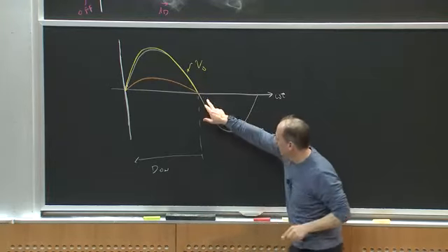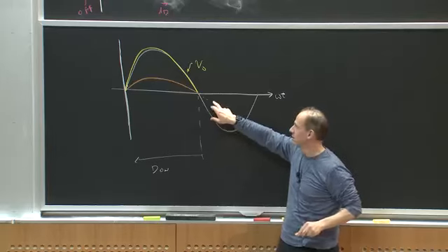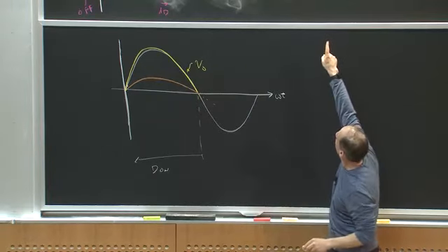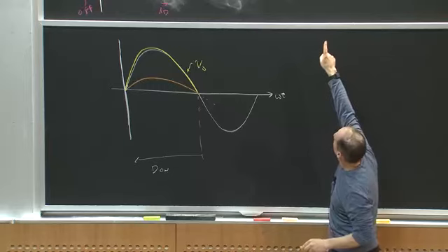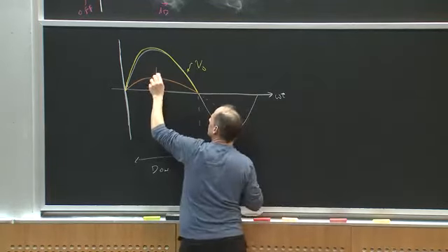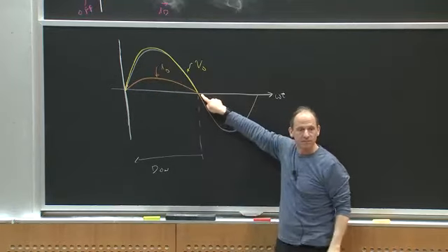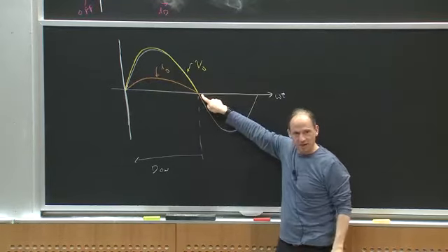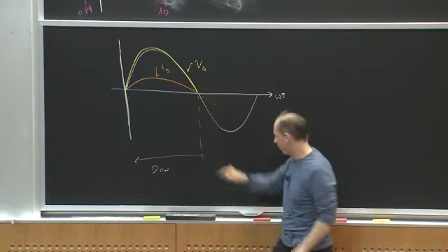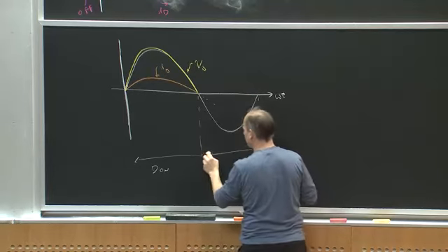Okay. Well, what happens when I cross this boundary? If I continue to assume I was in the same state where the diode is on, then I would have ID here go negative right here. But we know it can't do that. So what do I know? I know my assumption that the diode was on must be off. And so in this part of the cycle, the diode must be off.